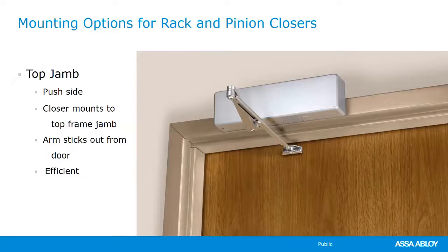Also, on aluminum storefront, you'll see Top Jam a lot, especially with the Norton 1604 closer or the Yale 51. Those closers fit perfectly on the aluminum storefront, the 2-inch frame, and you'll see Top Jam a bunch that way.